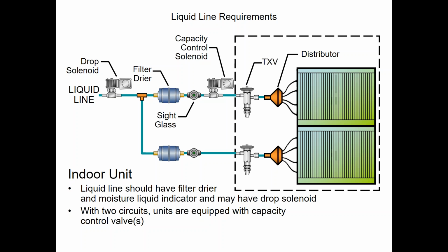Okay. So to calculate a weigh-in charge, we just simply figure out how much additional liquid pipe we have over the 25 feet. We look at the chart to see how much refrigerant is contained in whatever diameter liquid pipe you have, be it 1/2 inch, 5/8, 7/8, all the way up to 2 5/8. And you calculate that together for your total length of pipe.